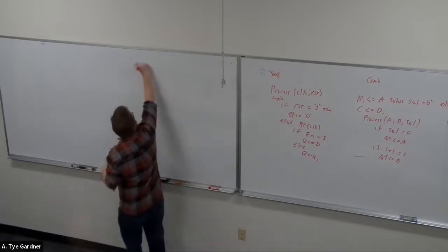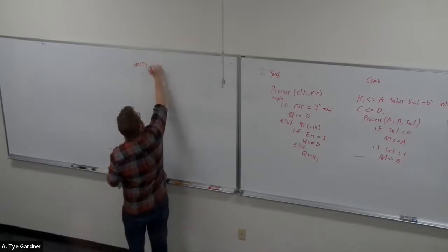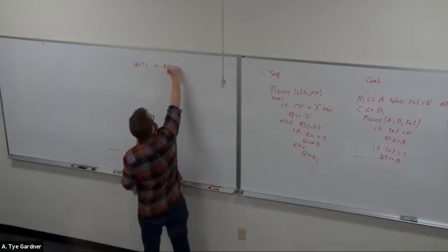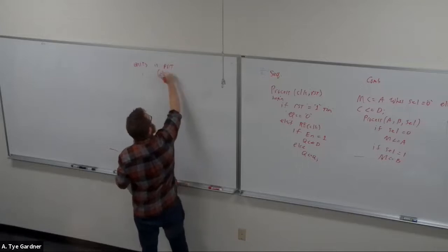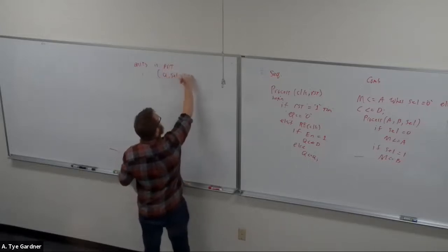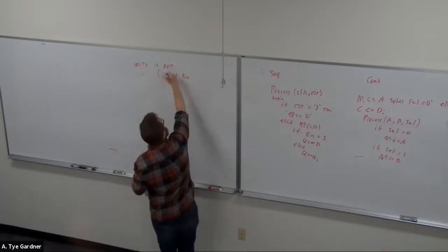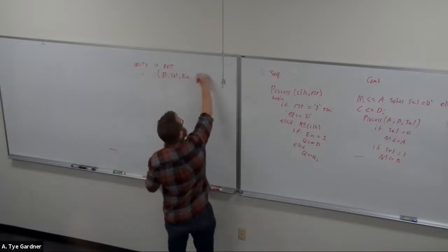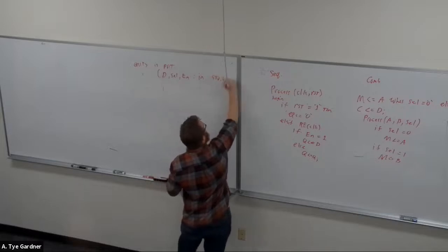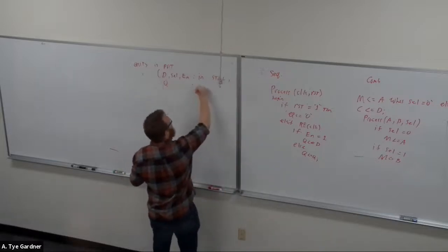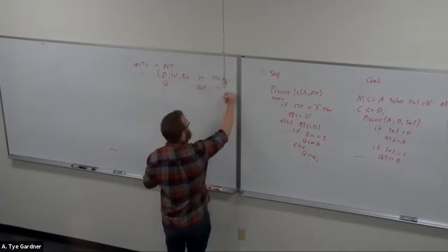So I have the entity, and it has ports of, sorry, I don't remember how to do this. Just Q, reset, enable, oh wait, Q's not an input, D, that are standard logic, and Q is an output, also standard logic.